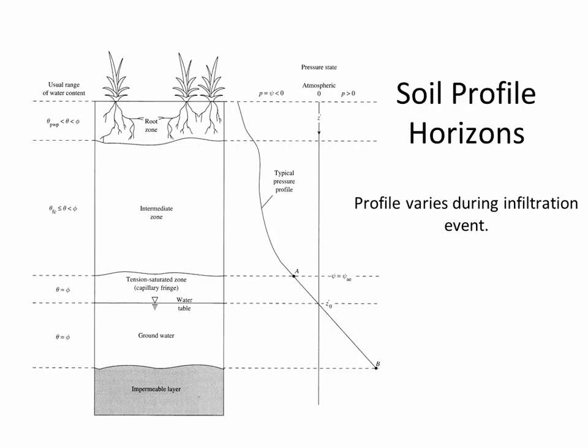But here in the capillary fringe, the water content is above normal because of the surface tension effect of water and the attraction that the water has for the small pores. So the reason why the water level is elevated in this zone is because the small pores are still full of water. Down here, all of the pores are full of water. Above this line, the large voids aren't saturated, but the small voids are still saturated because of capillary fringe.